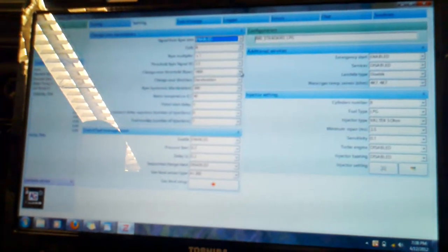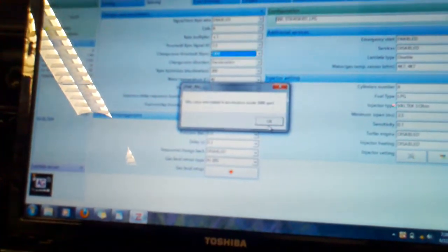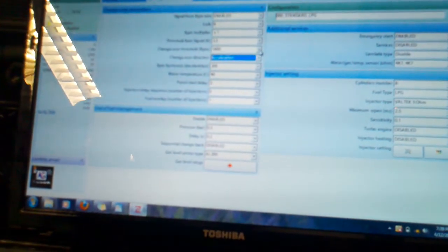Switch over RPM. This would be if we wanted to switch on acceleration or deceleration, what RPM we'd want it to hit. I'm pretty confident this will switch over just fine at idle, so I'm going to set it at 300. Oh, we need to set this to acceleration mode. So you can set it to switch over on acceleration or deceleration. I usually choose acceleration, but in either case, it's going to switch over to idle at 300 RPM.